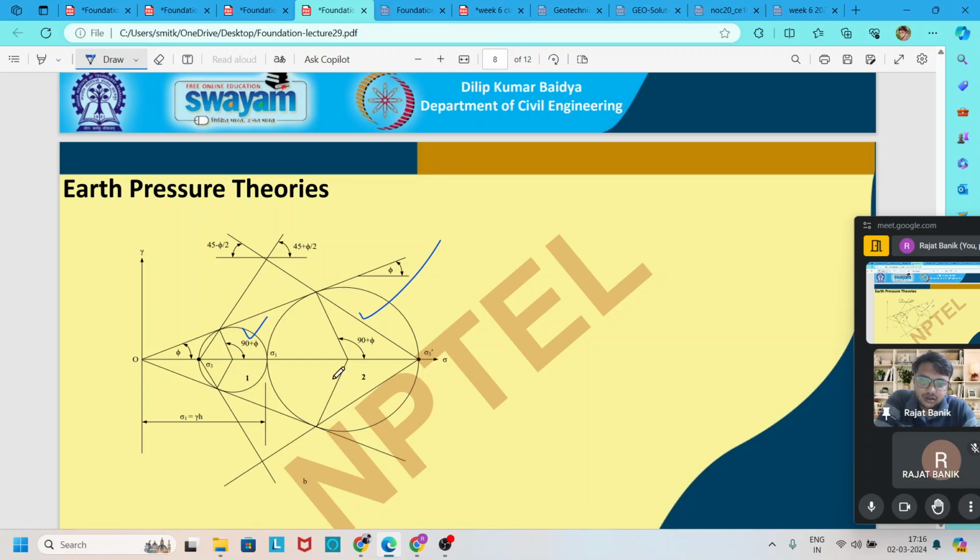By geometry and trigonometry we can easily find out, by Mohr circle, the critical angle of the failure surface. The critical angle is when the failure surface is tangential to the Mohr circle. We have to find this angle with respect to the horizontal earth pressure.